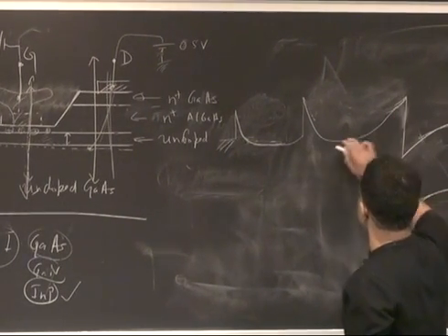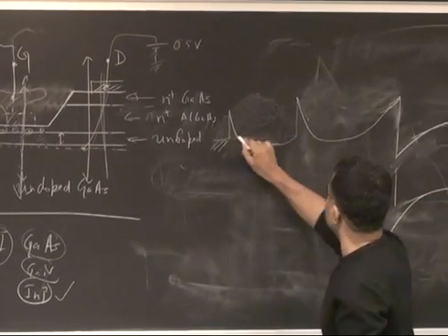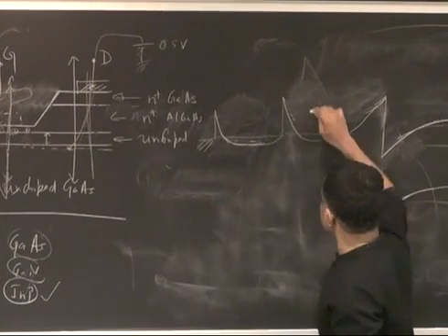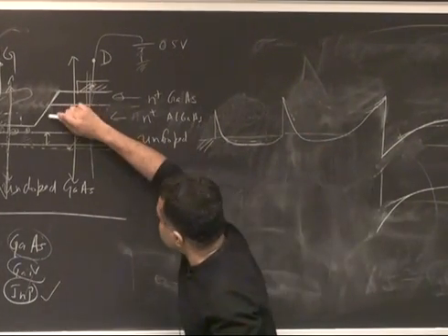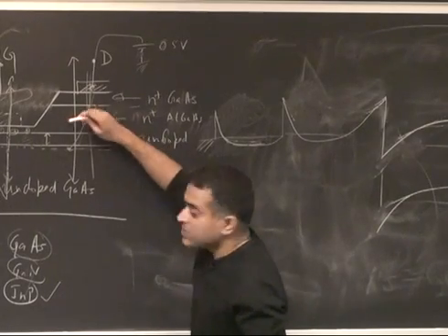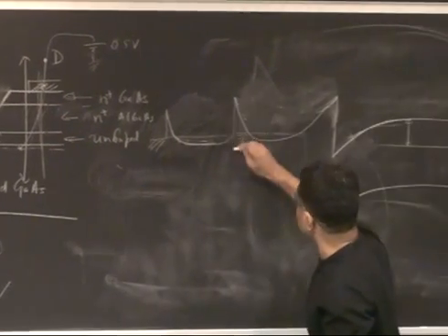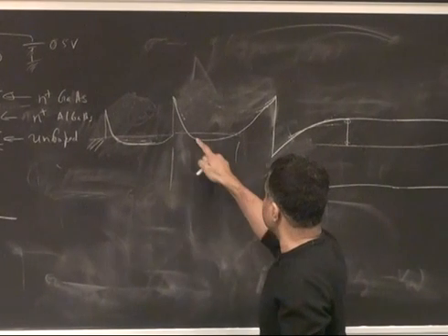It looks a little more complicated, but the whole game for having a very high doping and a thick layer is that in this region, you end up putting even more electrons. There are electrons here now in the conduction band. The conduction band edge of the AlGaAs region here goes below the Fermi level.